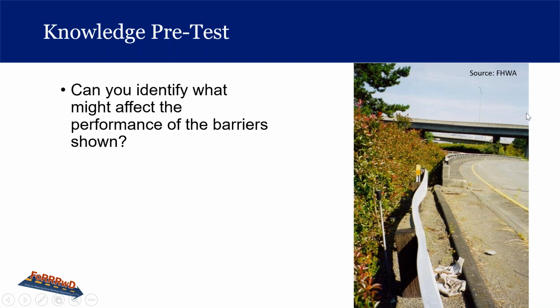So it might cause the vehicle to lift, and hit the barrier higher than normal. So if the tire stays on top of it, it's saying it would hit this, or the car would be up higher and do more damage that way. And the guardrail might lead the vehicle into the end of the rigid bridge rail. And the bridge rail, the curb and parapet might cause some instability in a vehicle. So that's what it's saying there. So yeah, obviously there's a problem there, right? So we need to know. So we'll talk about these sort of issues and how to prevent them in this chapter.